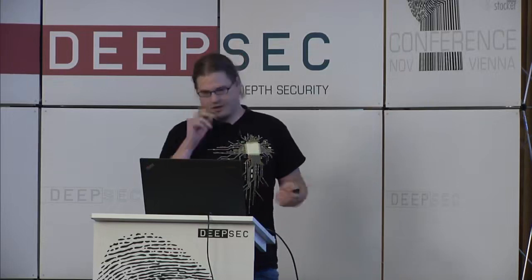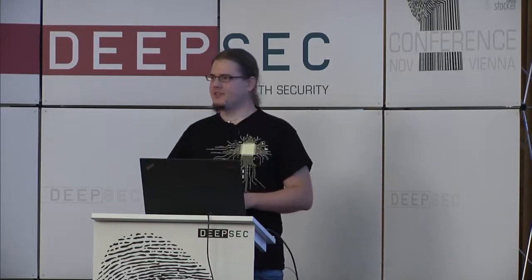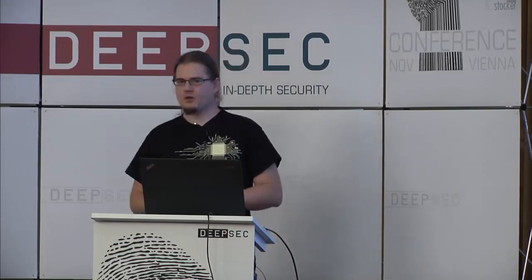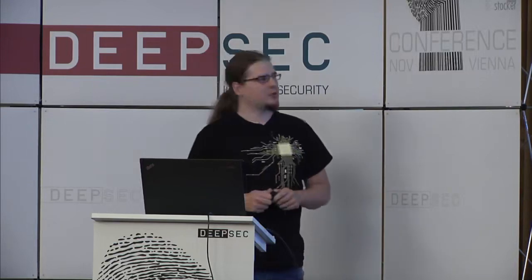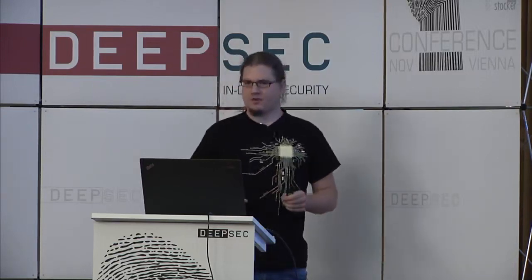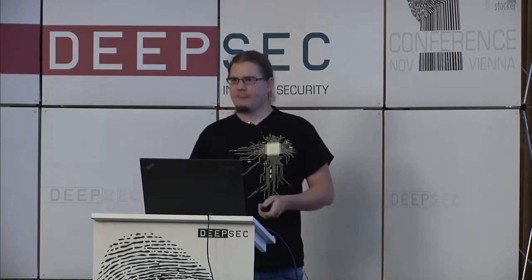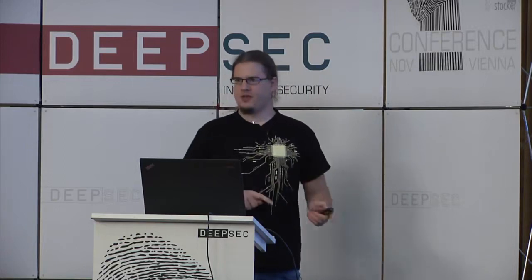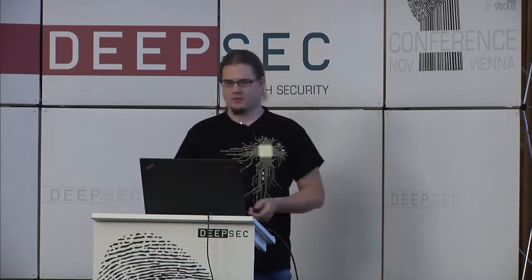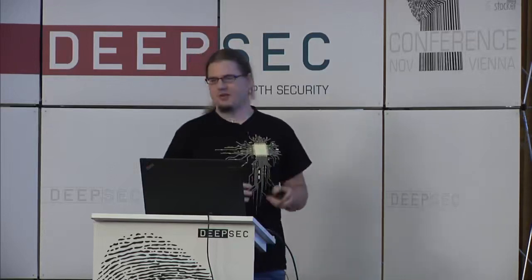It's not always that easy. As you can see down here, some of the vendors are using one-time programmable versions of this chip. One-time programmable is a little bit tricky here. One-time programmable means the chip you get from the vendor has a memory where everything is 1s. And when you program it, you can change a 1 to a 0, but never the other way around. So this is one-time programmable. You can modify the firmware, but just in a very limited way.